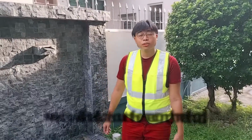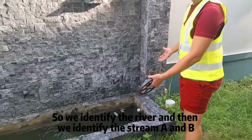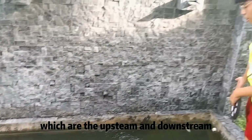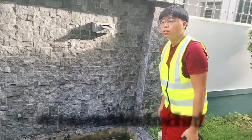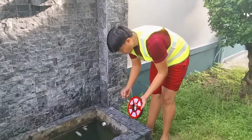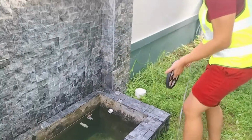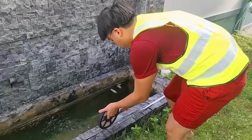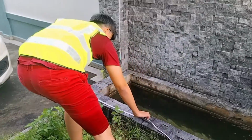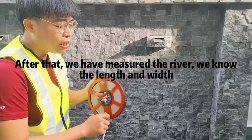Next, I will talk about the second method, which is the floating method. So we identify the river, and then we identify stream A and stream B, which is the upstream and the downstream. After that, we need to know the width and the length of the river, so we measure it. After that, we have measured the river, we know the length and the width.